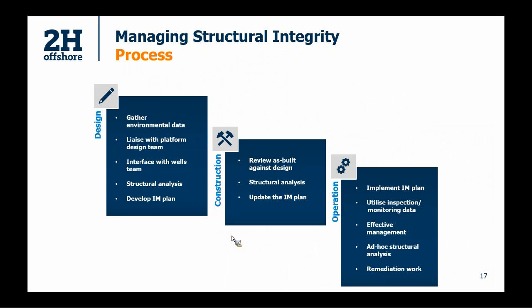Effective management, so that comes back to the holistic approach, multidisciplinary teams working together and sharing that information. Potentially ad hoc structural analysis, so again, if you do an inspection and you see that there's a centralizer missing, you might need to do structural analysis to figure out what effect that actually has on your system. If the centralizer is lower down in the system, it might not be a big problem at all, because a lot of the time the lateral motions have dissipated towards depth. So a centralizer that's missing at the bottom might not require analysis and certainly would be unlikely to require remediation work. However, if it's a centralizer that is at the guide either side of the sea level, then yes, that one's likely to result in remediation work being required.